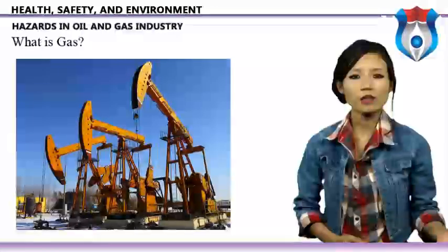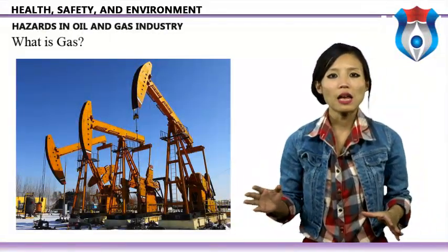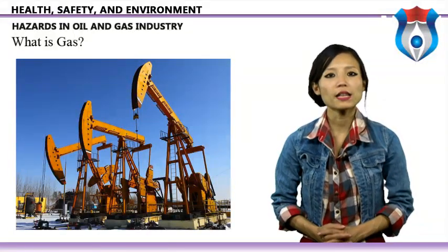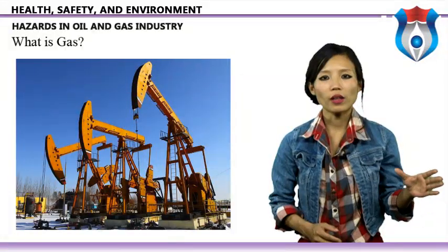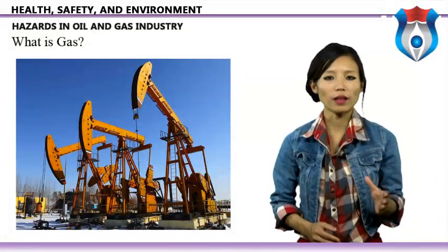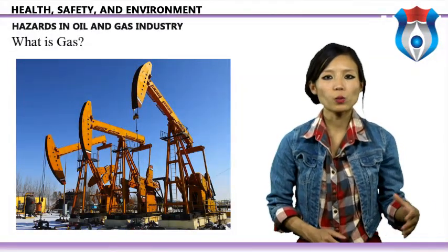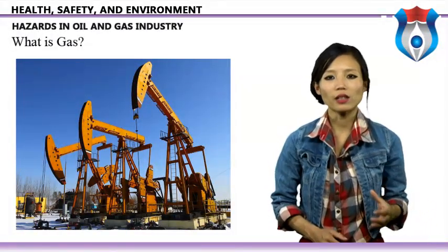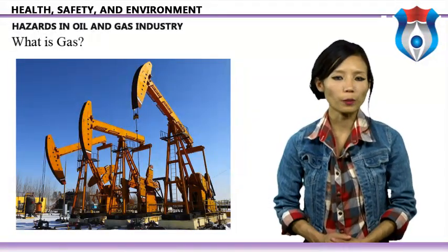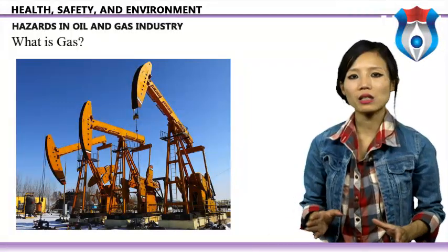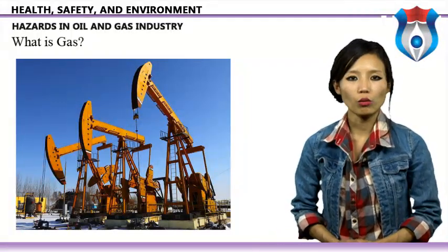Whilst different gases have different densities, they do not totally separate into layers according to their density. Heavy gases, such as hydrogen sulfide, tend to sink, and light gases, such as methane, tend to rise, but their constant motion means that there is continuous mixing. They do not behave like liquids. So in a room where there is a natural gas methane leak, the gas will tend to rise because it is lighter than air, but the constant motion means that there will be a considerable concentration at floor level. This will happen in perfectly still conditions, but if there are any air currents, the mixing will be increased.